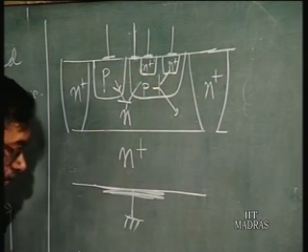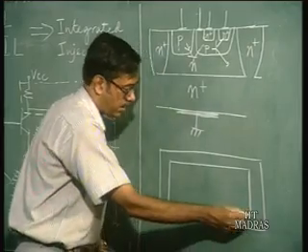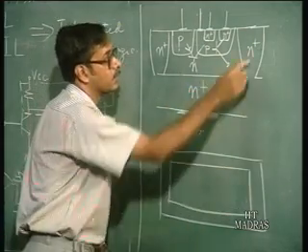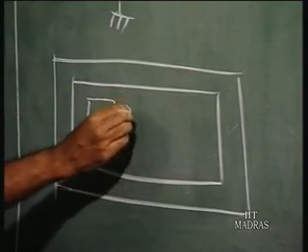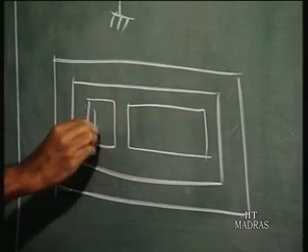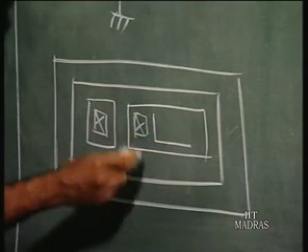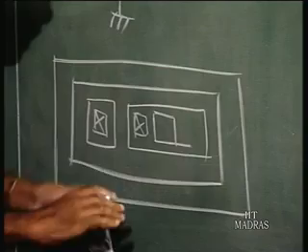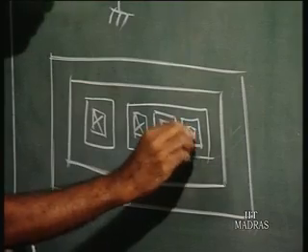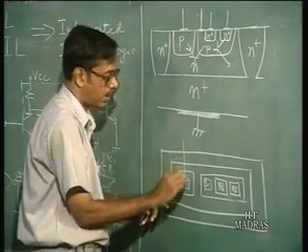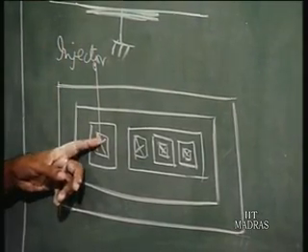Okay. I will also draw the top view of this cell because we shall be doing a lot of this. Okay. So, this is the n plus, which is the guard ring sort of. I shall also explain later why we require a guard ring. So, you have these contacts, sorry, these are the collector regions. Okay. So, this is the injector contact. This contact is called the injector contact. That is basically the emitter of the PNP transistor, that is called the injector contact.